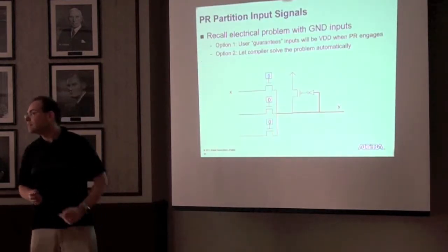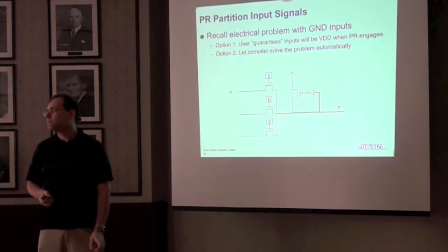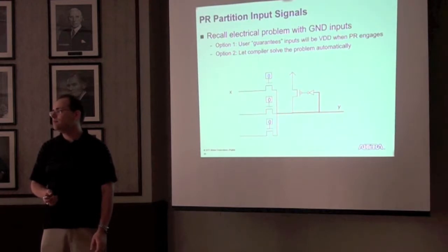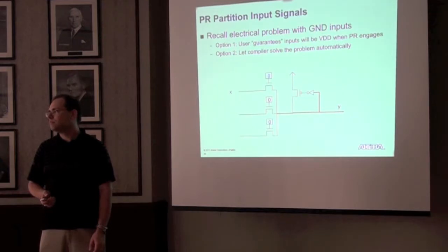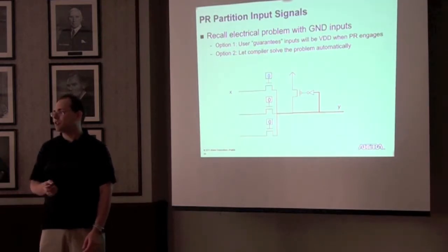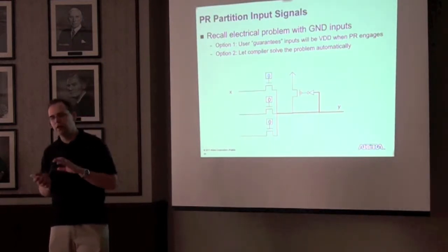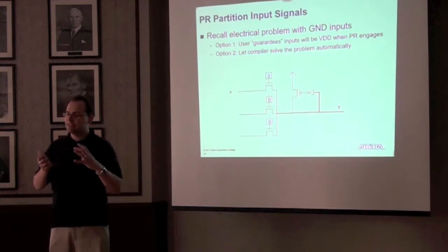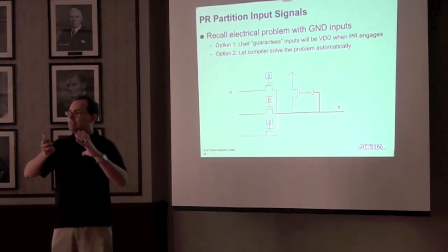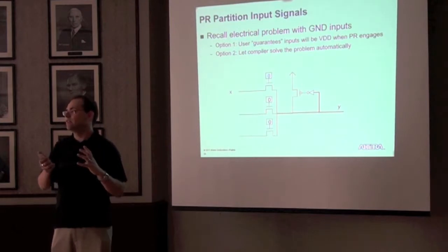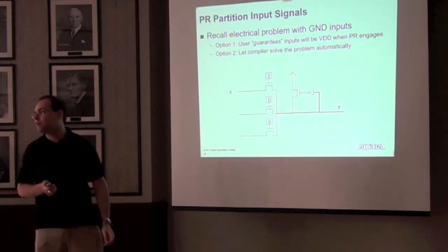So, yes? Speaking of the routing resource sharing, I'm a little bit worried that when doing initial floor planning, because of the rectangular nature, you create blockage. So is it possible to reserve some feed-through kind of resources? Yeah, I'm going to be talking about that shortly. The question is, when doing a PR design, worrying about blockage. What happens is that even though you define a region on the chip, it doesn't actually represent a hard wall for the static region. And I'll be showing how routers work later.